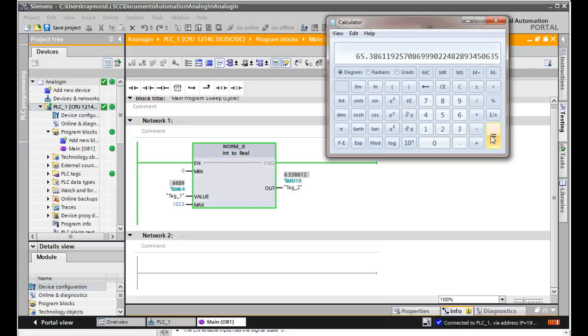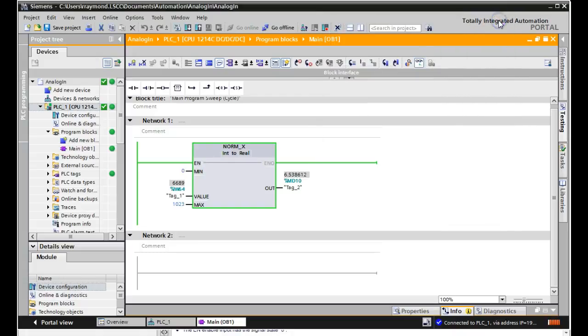You'll see what it does for you, and it's doing all that automatically. It's taking this, which is just an oddball value, and doing the transfer function for me. Then I could convert this into degrees or whatever I need to do. So if 10 volts equals 400 degrees, I could convert it so it would display degrees too. Are we okay? So that's analog, guys. It's really, really neat.